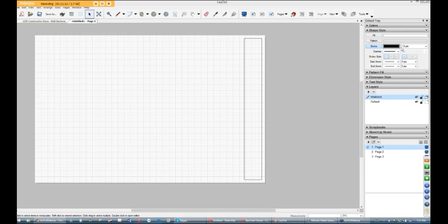And I'm going to set a stroke here at 1.5. That's fine. Fill is turned off. That's fine. And type in an L for line. Again, like SketchUp, you don't need to hit enter. Now, you can set the defaults for these line weights right now. What I like to do is pick the tool first and then set the defaults.